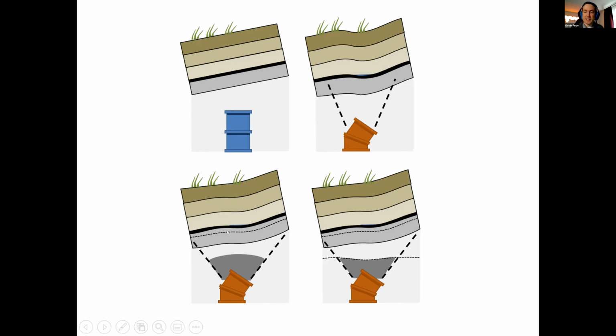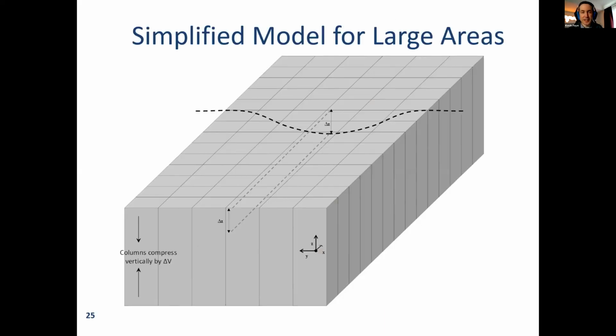And in the case of Maxey Flats, we actually did 2 different geogrid layers. We had one near the surface to deal with the very large, very shallow craters. And then we did one deeper down to bridge over some very localized depressions that were creating that very deep discrete crater that I showed earlier. So we have both mechanisms addressed with this design.